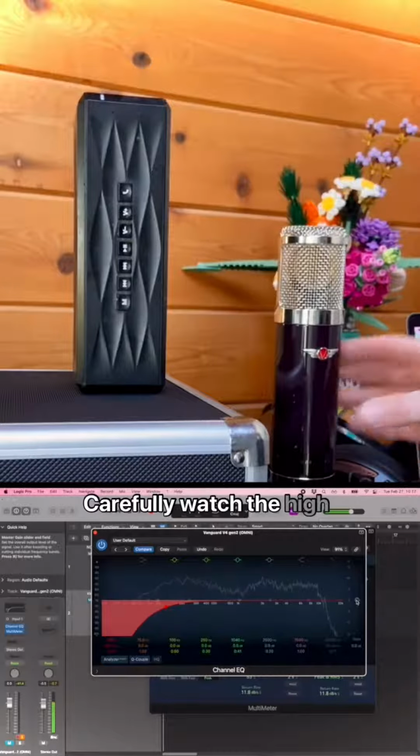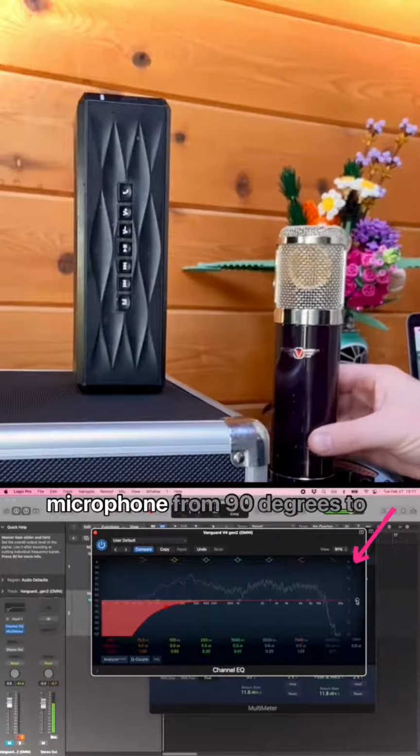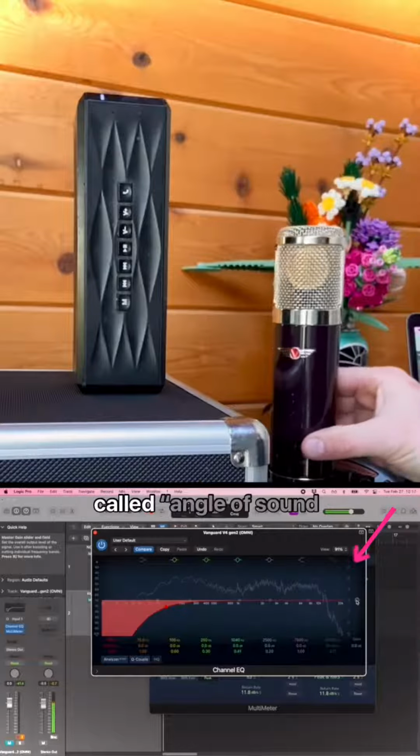Carefully watch the high frequency area of the response of the frequency analyzer. Watch when I shift the microphone from 90 degrees to facing the speaker and how much the high frequency changes. The nerdy reason for this is called angle of sound incidence.